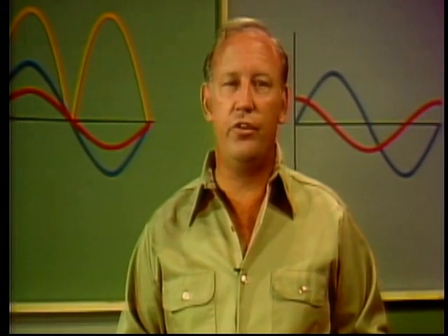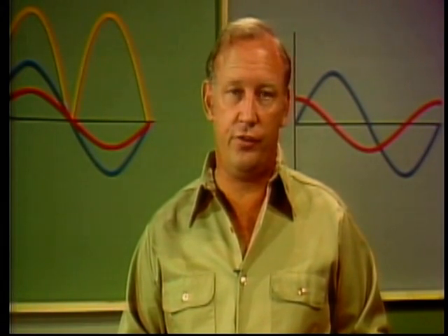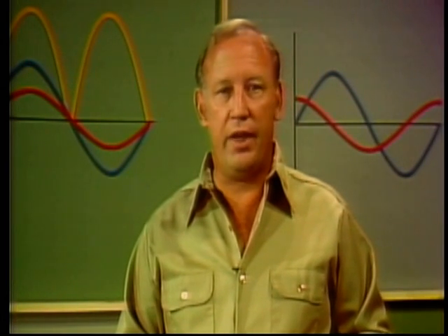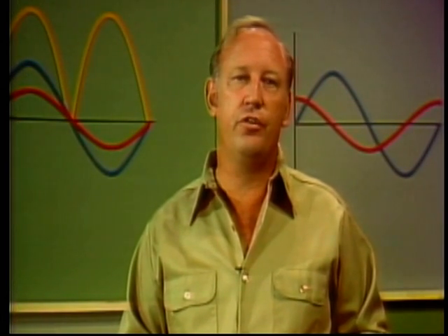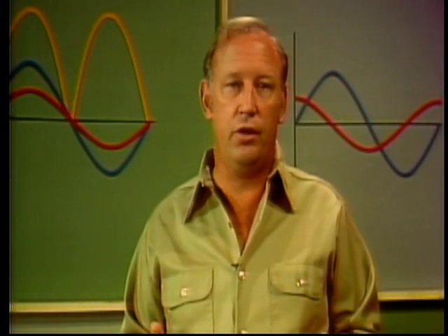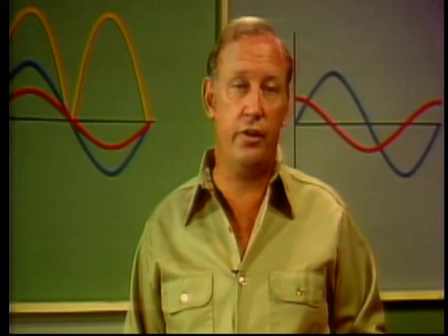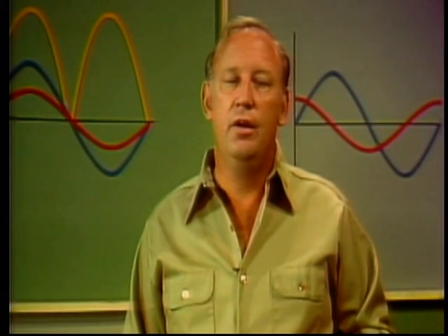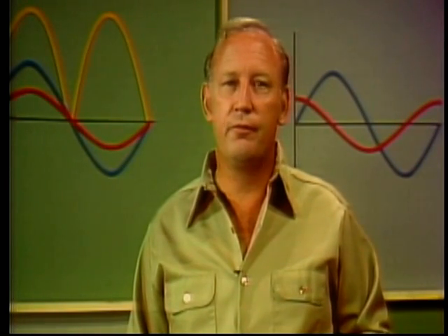When we talk about the effects of inductance, we generally use another term, inductive reactance. Inductance, as I said, is a physical property of all AC circuits. Inductive reactance is the measure of the opposition to current flow that's created by inductance. Because inductive reactance opposes current flow, it, like resistance, is measured in ohms. Now, let's look at just how inductive reactance limits current flow.